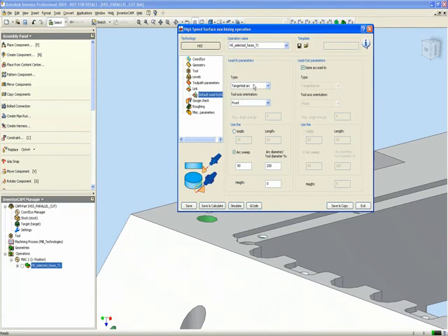As you can see right now, I chose the option of tangential arc, and that is the default option. If I were to choose the option of vertical tangent arc instead, then the tool will come in vertically from the top, and only then arc its way in.